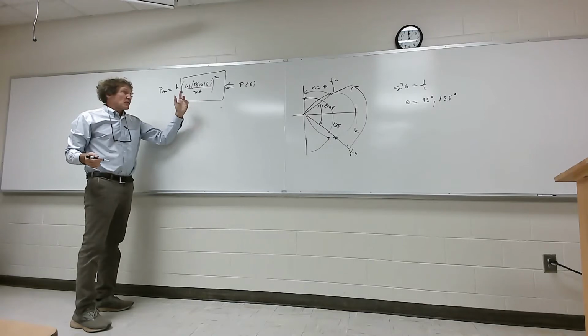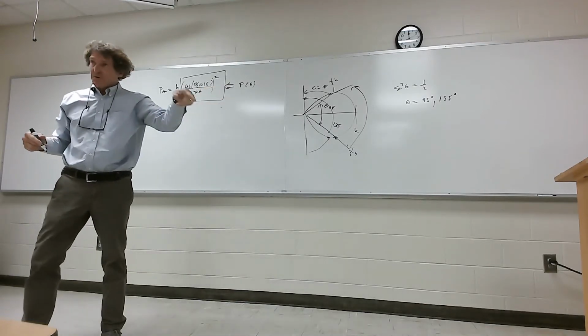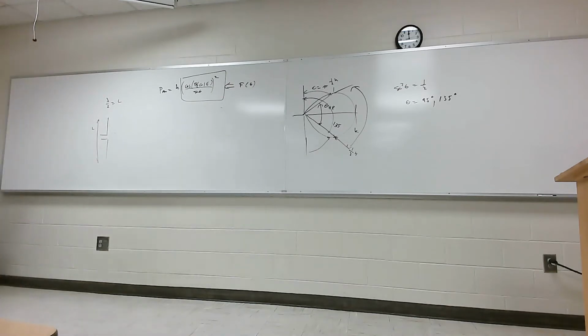But if it was the arbitrarily long dipole where you had the cosine of beta L over 2 coming off that, then you don't know. It gets much larger than 1. Then you have to evaluate where that angular function is a maximum and know the maximum value. And you have to divide that into the angular function to get a normalized value. You all follow me? All right.